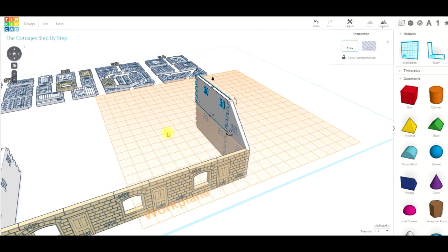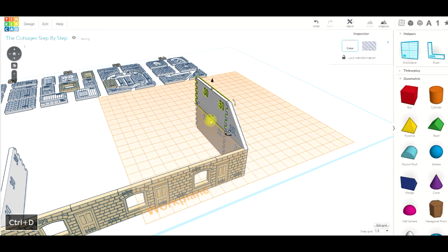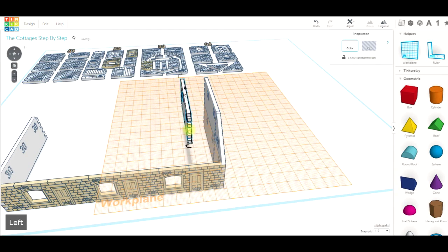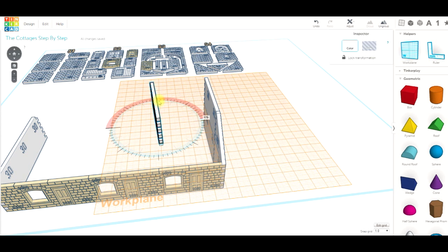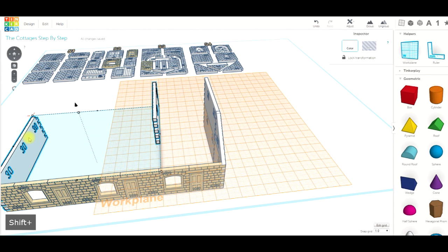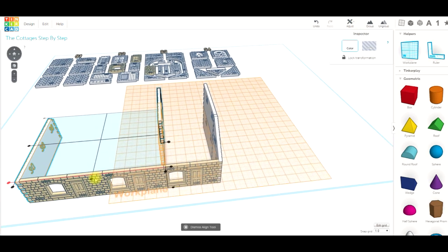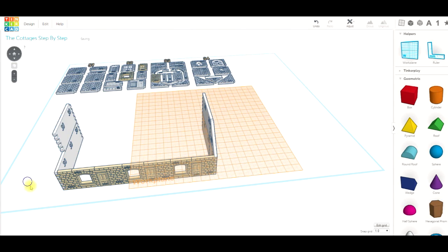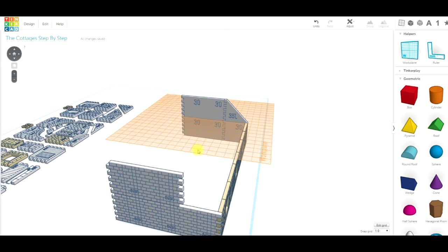So I'm going to do this properly. I'm going to press Control and duplicate. And just while looking on this face, I'm going to press the left. Just anywhere there, I'm just going to spin that round because it needs to be the other way, obviously, 180 degrees. I'm going to shift and click the other part, so I've got the two parts. Adjust, align. I'll need to just roll out because it's that little line there I want. And there they're in, exactly opposite this.